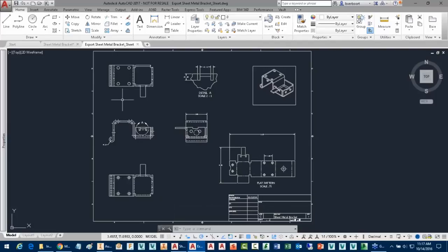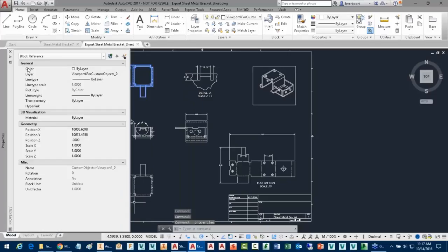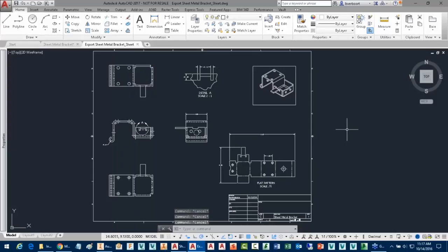Right, so the source of the information is Inventor, but what we've done here is we've really just built out a series of blocks in mass for all the views and the different view types that are listed here. So again, just a quick way to do an export. I prefer to keep the documentation tied into a common DWG, but if you did need to get the information out and have it be more editable, then here's a way that you can do it.